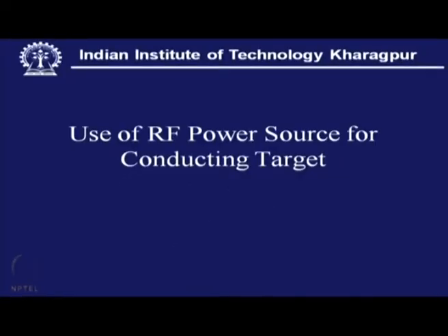So, it is actually a blocking capacitor and this match box for fine tuning of this power supply with this resonant circuit in tune with the plasma, so that the best possible way of power transfer is possible. However, these are high order technical complexities, but this is actually a complicated hardware of the sputtering system one can also realize.